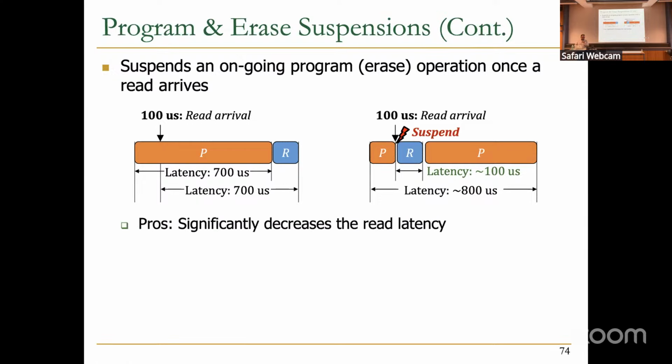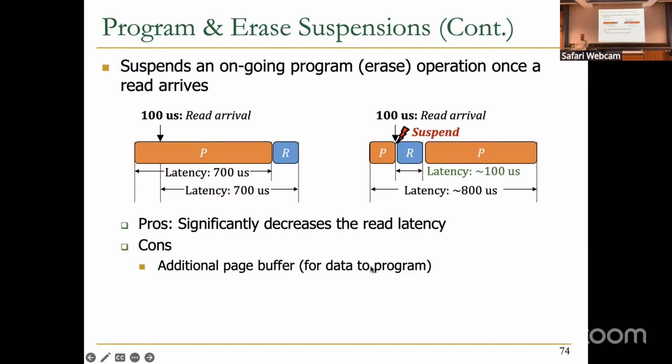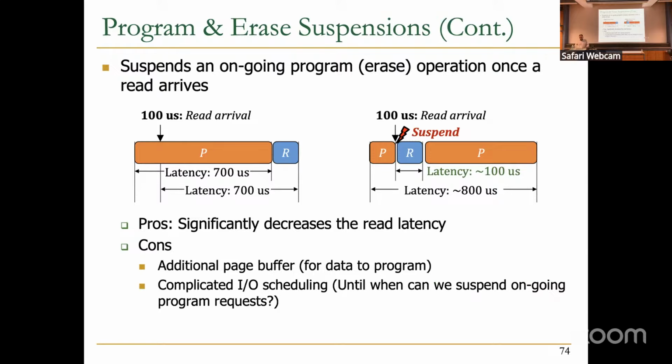So it has pros, like significantly decreasing the read latency, but it comes at the price of an additional page buffer for data to program. So now when you want to suspend, there should be some additional buffers, such that you can do that suspension. And it also complicates IO scheduling for when we can suspend ongoing program and erase. This comes at the price of a fairness issue, which we're going to get to later.